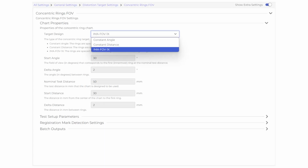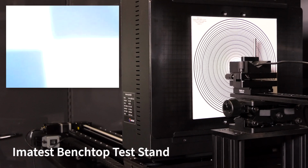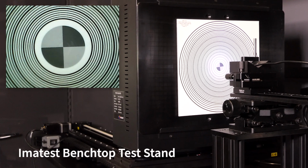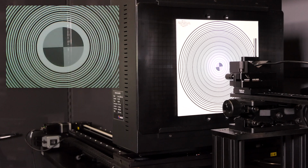Imatest supports two main types of concentric ring targets: constant angle and constant distance. A default preset for the IMA FOV 1X chart is also available in the Target Design dropdown. This chart is inspired by the ISO 8600 standard and is an example of a constant angle target with rings spaced 2 degrees apart beginning at 30 degrees for an intended working distance of 50 millimeters.